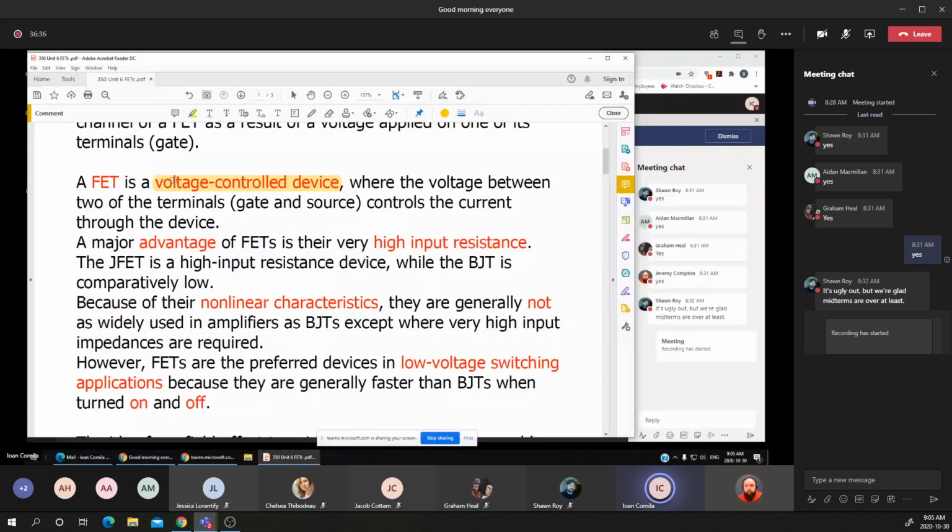Sometimes this is referred to as an ESD, electrostatic discharge, that may damage the FET or the field effect device. Remember that another precaution is that sometimes we may have to wear a bracelet, or a connection between our body and the physical ground of the bench of the circuits, and that's why it's a special way of handling those devices.